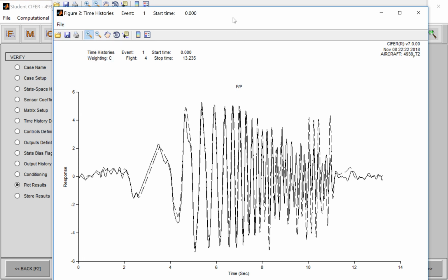In your report, I would love to see your time domain verifications. You don't necessarily have to do this for every one. You could if you'd like. Every time you run one of the models, you can show me the frequency domain result and the time domain result. You could also do this only for the one in which you have the highest confidence, the one that gave you the best frequency domain result. Then go ahead and do the time domain verification there.